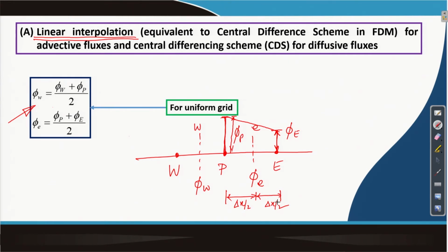But as we mentioned earlier, you do not essentially need to have equal distances, and this is one of the big flexibilities of finite volume technique, that you can have unequal distances at your convenience, because very often in fluid flow problems we prefer unequal distances when we have to capture strong gradients. So, we put a very fine grid in order to capture large gradients, and then we tend to put a coarser grid where the gradients are decaying and becoming weak. So, we do not have a large number of nodes in such regions, because that saves us computing effort.